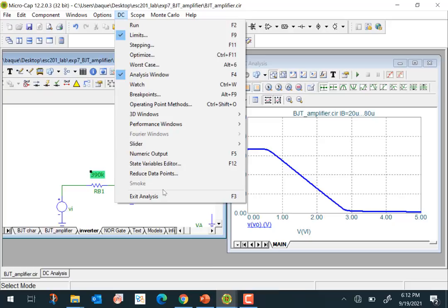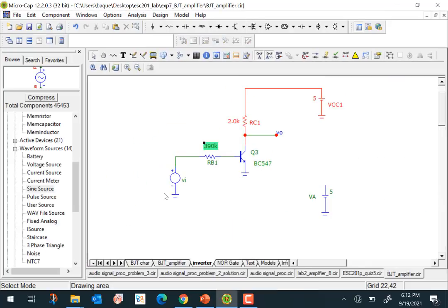And so let's come out of here. The other thing that one can do is a transient simulation. So one can apply a step here. If one applies a step, say you go from 0 to 5 volt, then this will of course go from 5 to 0. But it will not go from 5 to 0 abruptly. You will see that there is a delay here, because the transistor has internal capacitances. And they have to be charged and discharged, and that's where you see the delay occurring here.